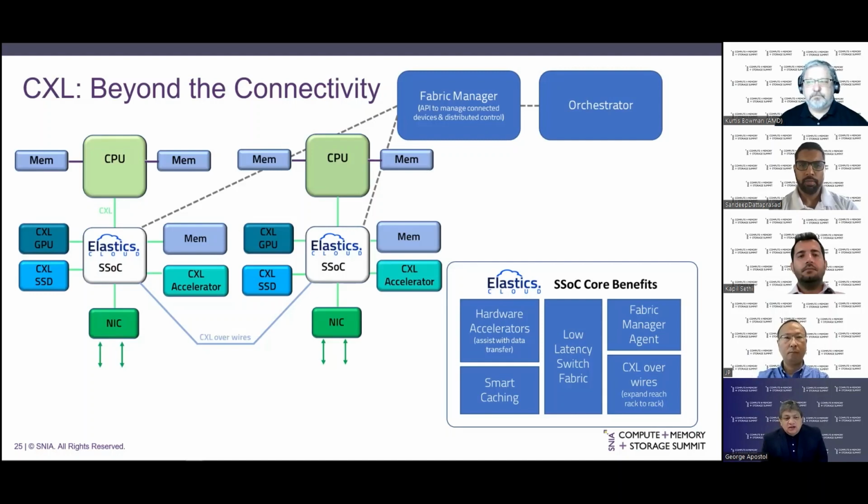And we tried with SRIOV, which one could say was pretty successful, and then also with MRIOV, multi-root IO virtualization, which posed a real challenge because of the PCIe protocol and the limitations of that protocol. It was difficult to have multiple processors now connected to these IO